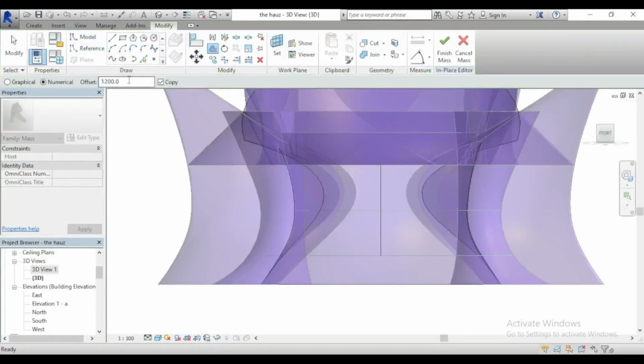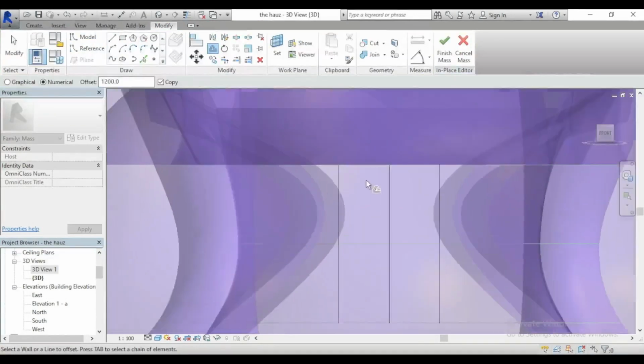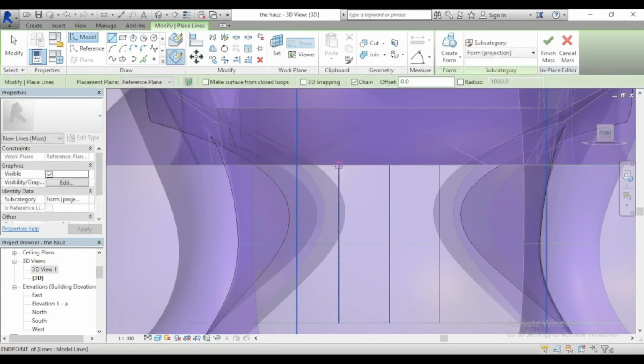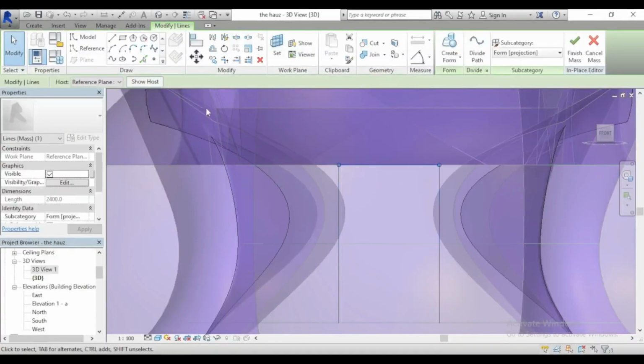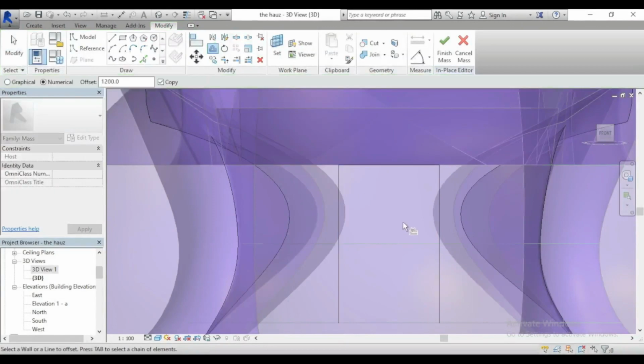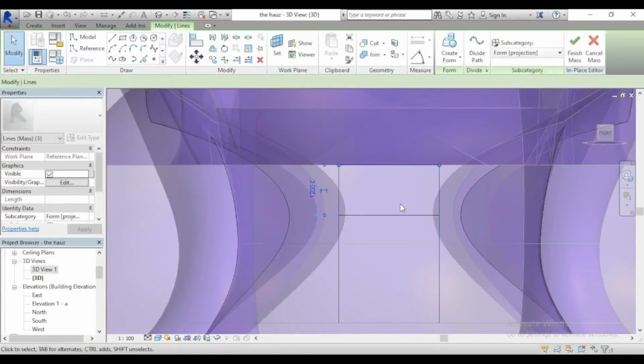So you click it and edit it, then you start creating your lines. Create this line, then I'll set 1, 2 around. Just do what I'm doing on the screen, and then create the horizontal, and then offset that horizontal by 1, 2, 1, 2, and then trim it.